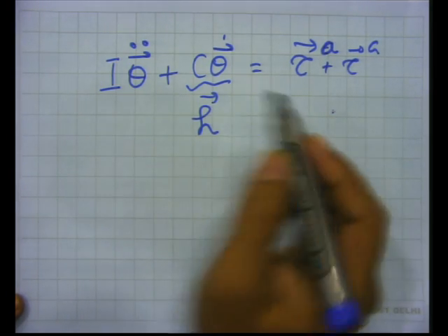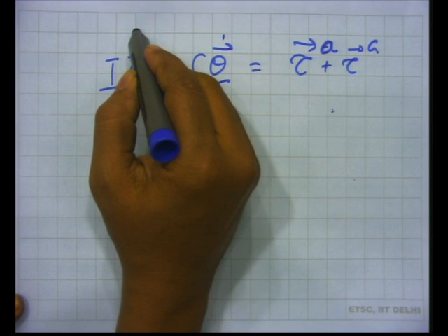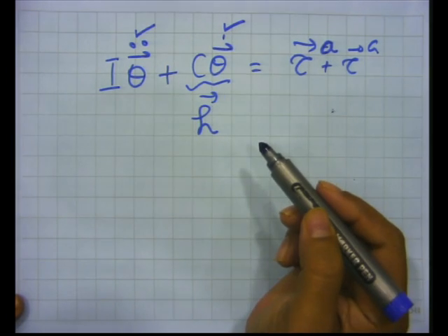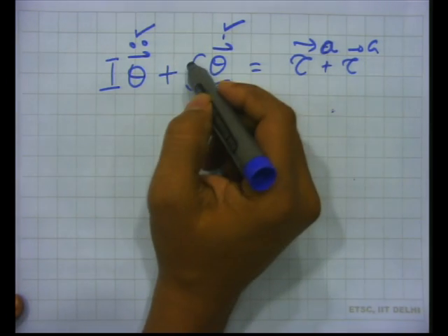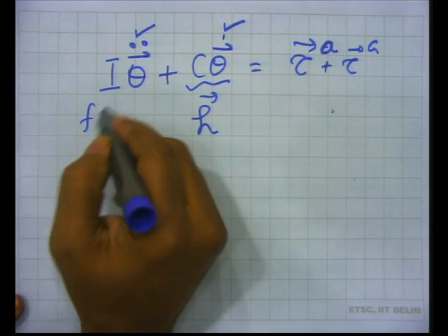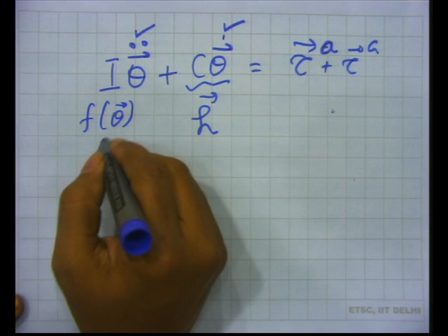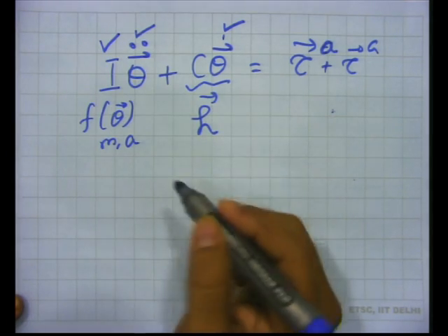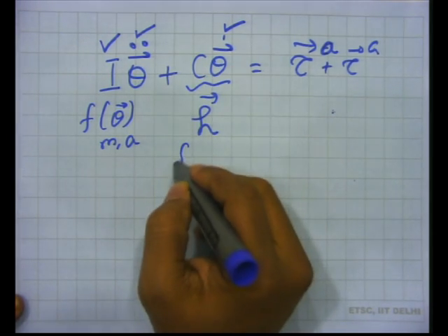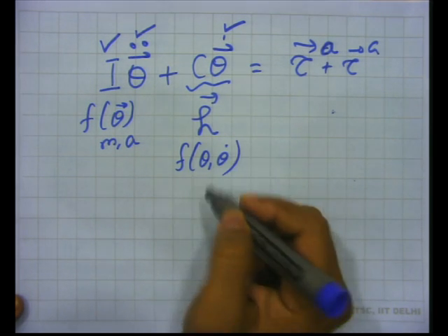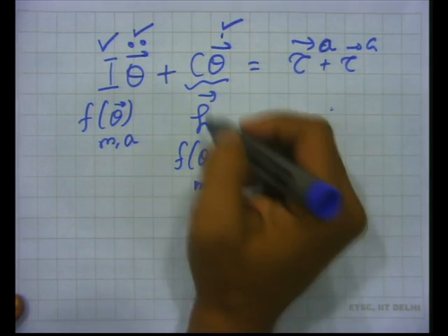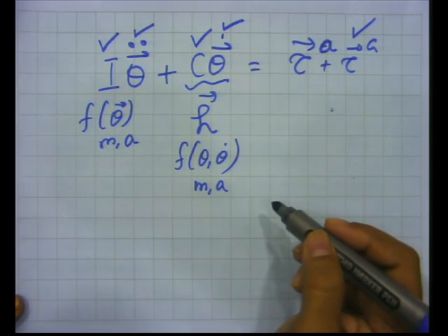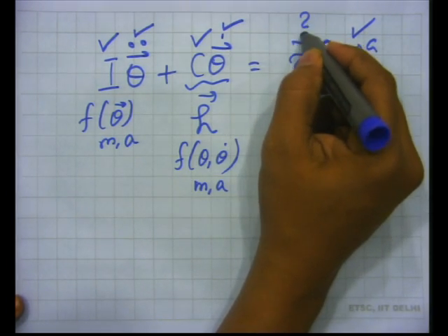Okay. And what we have done so far, we have provided the input theta double dot, that means I know how my robot should move. I have provided theta dot, I know what velocity it should move. I is a function of theta and mass, link length, etc. So, for a given system they are also known. Similarly, C is a function of theta and theta dot and mass, link length, etc. So, all those are my input parameters, so they are also known. I know whether gravity is acting or not. Okay. So, finally, what I have calculated is this one.